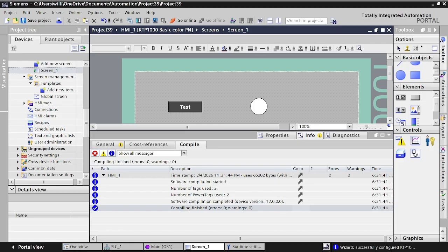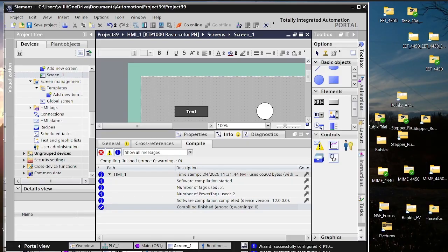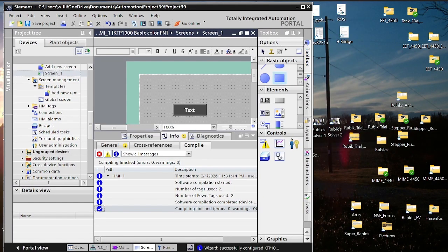And you run it. You run this off to one side, and you run your HMI off to this side. So at this point in time, you have your logic over here, and you have your window with your HMI over here. And it's live, and it works. Click over here, the bit turns on in the PLC. And you see the light turn on, and then it does whatever, okay?